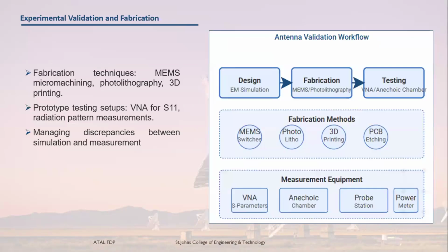Yes, this is the external validation. After we bring out the antenna model, what do we do? Yes, we fabricate it. The antenna should be fabricated using photolithography technique, and we test it. Once the antenna is designed and fabricated, is it over? It should be tested. Can you tell me one instrument which we use for measuring the return loss characteristics or S11 characteristics?